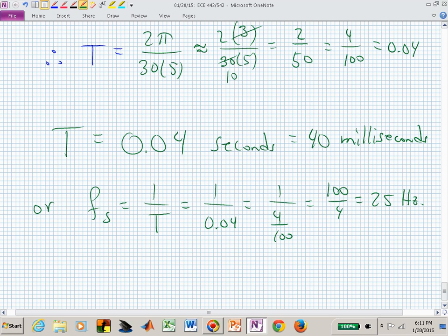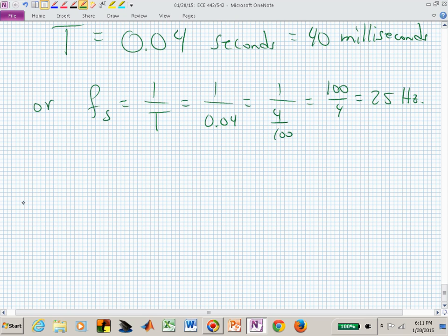Okay? And we'll probably see that illustrated a little bit more as we go through the class, but for now, I think your rule of thumb is, oh, just sample at 30 times the closed loop bandwidth, and we won't really worry too much more about that decision. Okay? But that's the reason it's there, because we need more than just the information content in our waveform.